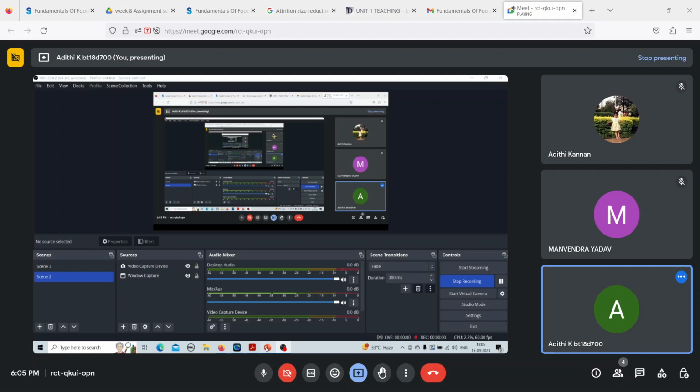Okay, the critical speed of a ball mill can be given as capital NC is equal to 1 by 2 pi root of g divided by (R minus r), where g is the gravitational constant 9.81 meter per second square, capital R is the inside radius of the ball mill, and small r is the radius of the balls that we have inside the mill. So this gives you the critical speed in RPS, that is revolutions per second.